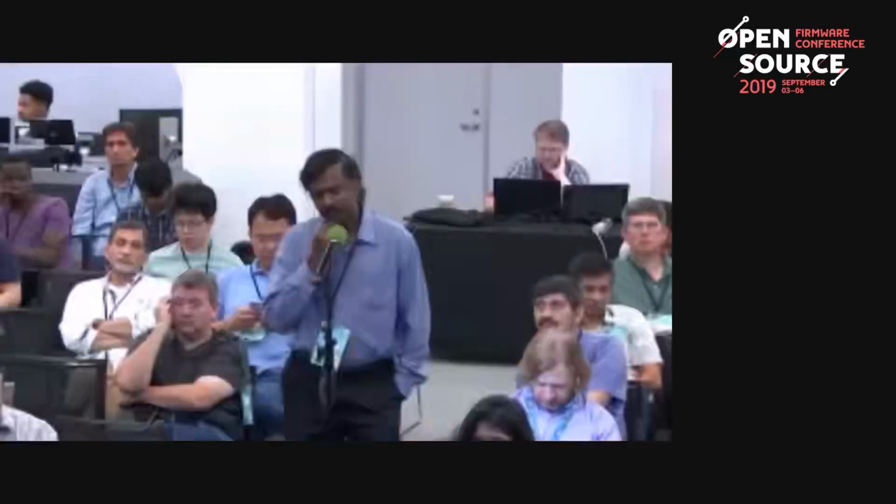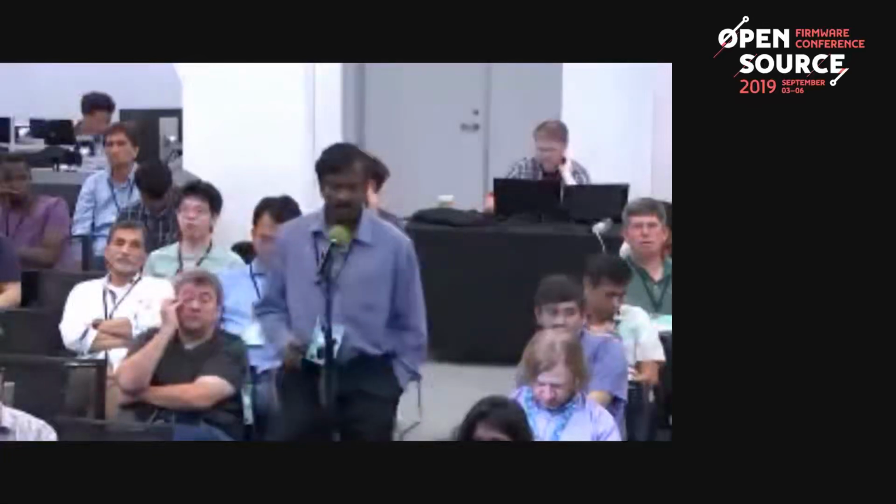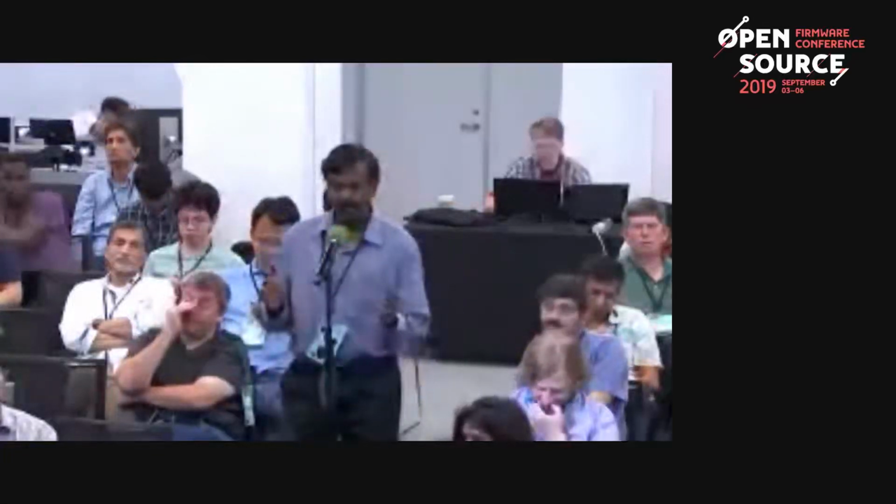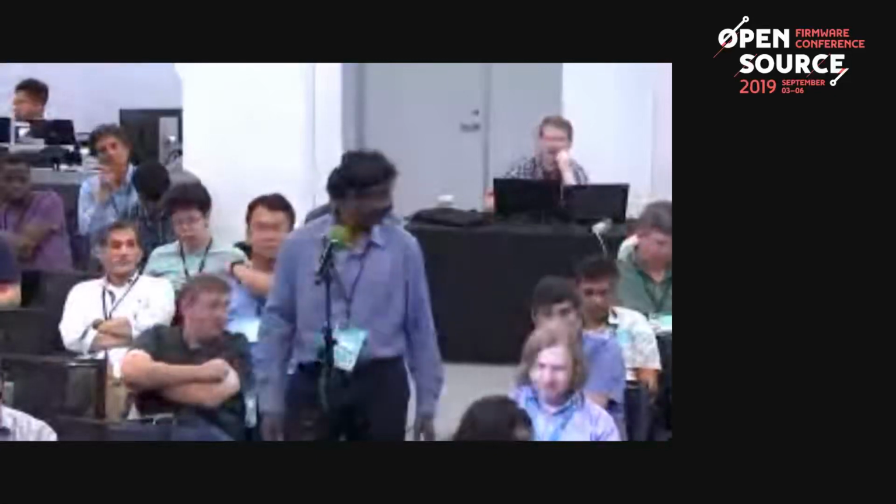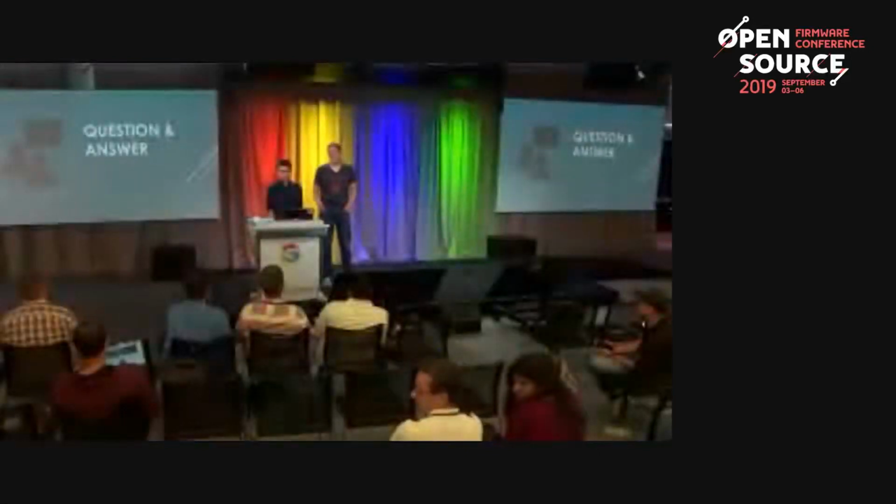And the second thing, just to add to this point on boot time. The majority of the boot time is taken by ECC init. When you come up at a cold boot, memory is not initialized with zeros, which means the ECC doesn't match. I know that one very well. That's a major time-consuming task, to go and write all zeros so that the ECC word matches with the data. Ryan, is most of our boot time taken up with ECC init?